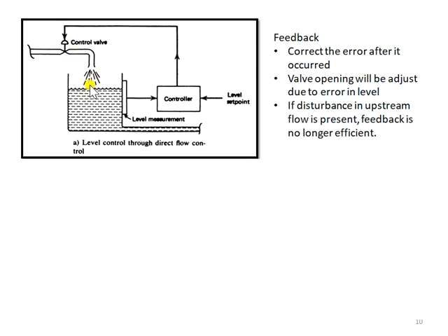Let us give one scenario. Let us assume the water level drops. Once the water level drops, the controller can detect that the level is dropping, and therefore the controller will send a control signal to open the control valve. So the control valve will open and more flow rate will flow into the tank, which will cause the tank level to increase.